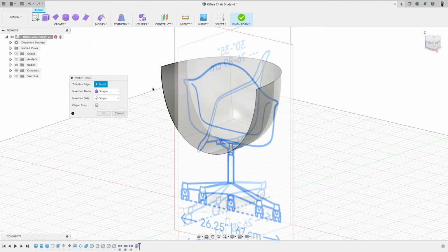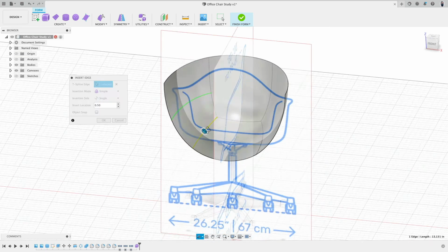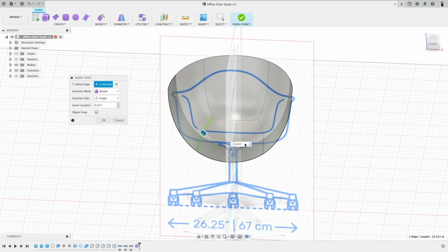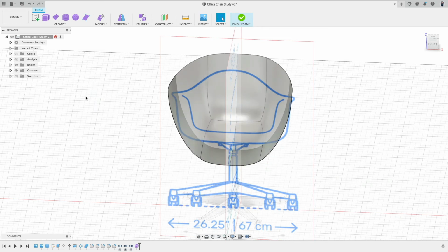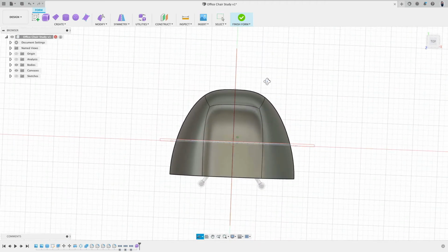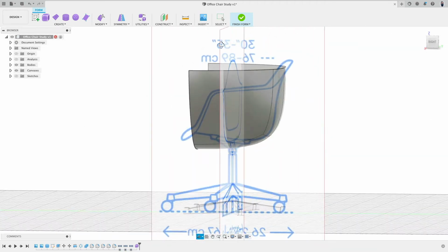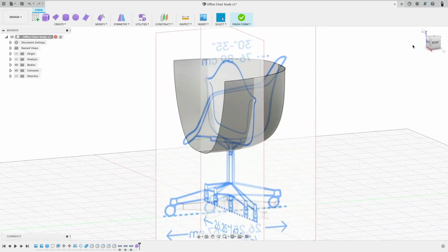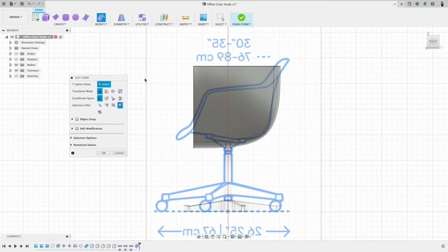Let's go to Insert Edge. Other side to there. So minus 0.5. Very good. And then insert point. Now we can continue this to there. There, now we straighten this a little bit. You see? Not too complicated. If we go to the side, let's see what we can do when we select just these points and drag those down.